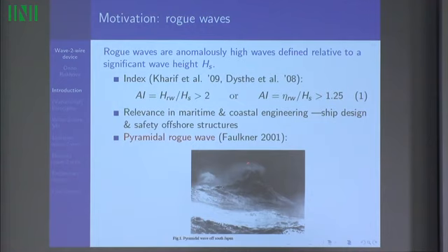So this is a wave due to crossing seas in the sea south of Japan, and people always ask, this is about 10 to 15 meters high, because you can't see from the scale. But in some sense it doesn't matter. It's this definition which matters. If your ambient wave height is 15 meters, then your rogue wave height needs to be bigger than 30 meters. So it's a relative scale.